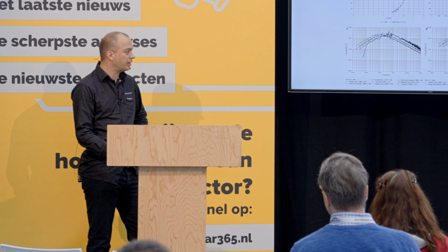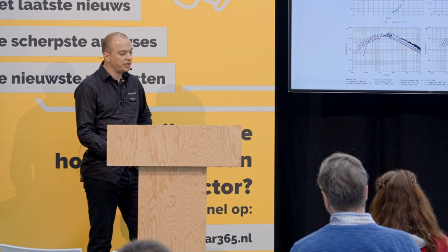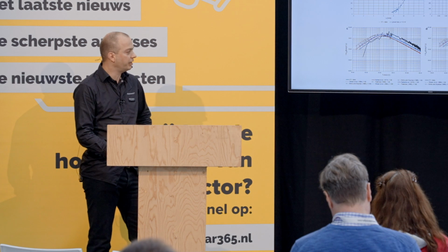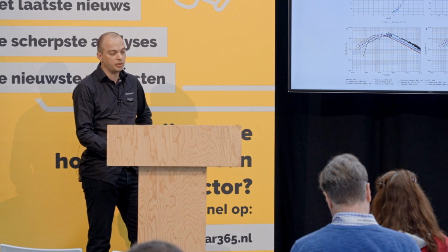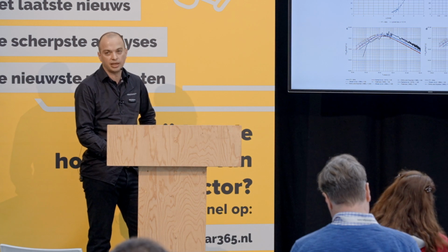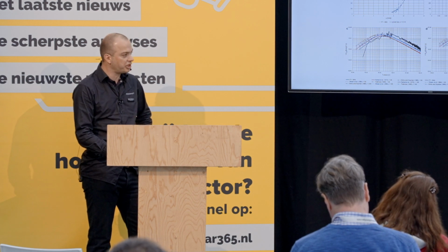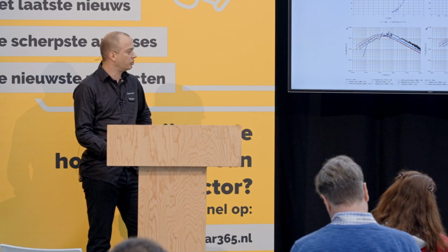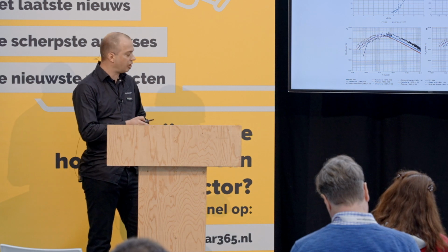The reason for that mismatch is that almost all wind tunnels around the world have been built for the study of conventional buildings at a scale of 1/200 to 1/400. Then just later they have been used for solar structures, which are modeled at a larger scale, because the pressure equalization needs to be modeled because of pressure taps. So that is the reason. And yeah, this needs to be taken into account. It's very important.